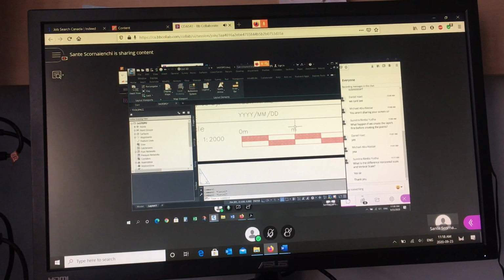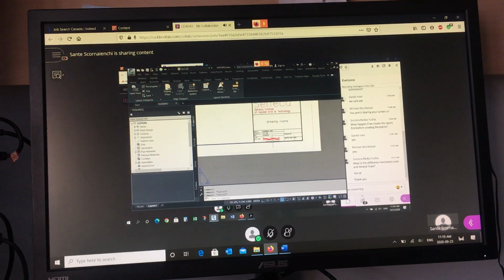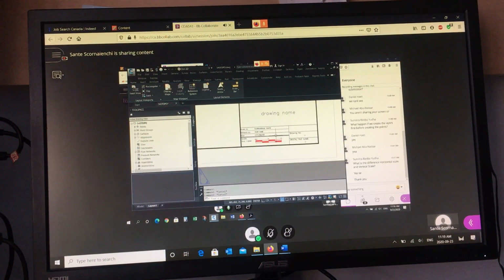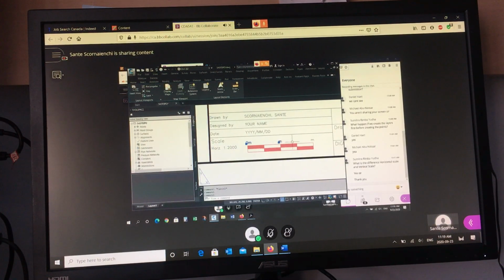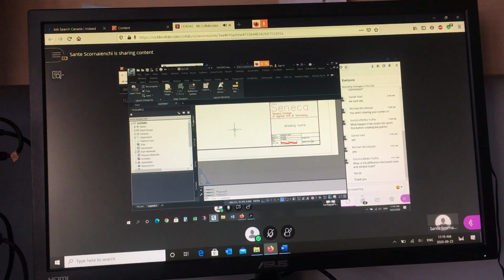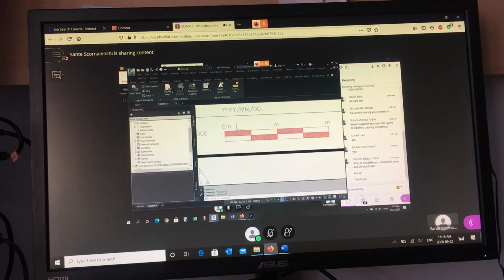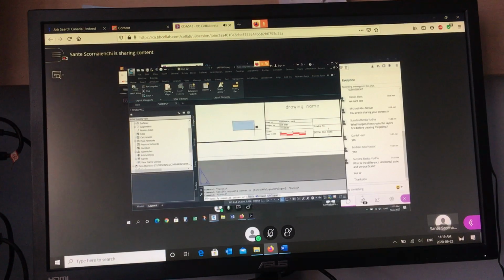Everybody understand? Right? This is in paper space. But the distances in model space have a scale factor, right? Half size. So the distance from here to here in paper space is not what the distance you see here in model space. So you need to determine in paper space, what does this distance from here to here represent in the viewport? Okay. And I'll give you a hint. It's either half the distance that you measure in paper space or twice the distance, right? There's a factor of 2 at play, either a half or 2. Right? 1 over 2 or 2. You need to figure that out. I'm going to leave that up to you. So what should those distances be?